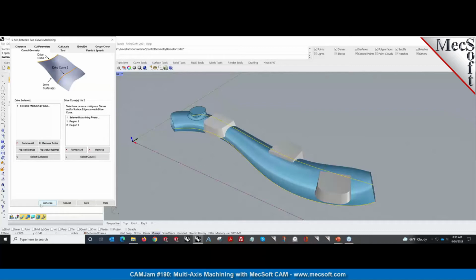You can think of it that way. But in 5-axis mode, apart from the X, Y, Z coordinates that we obtain from slicing, we also have the surface normals we use to actually position the tool along that surface normal. And then obviously there are some additional controls you can use to control the angles and the axes of the tool.